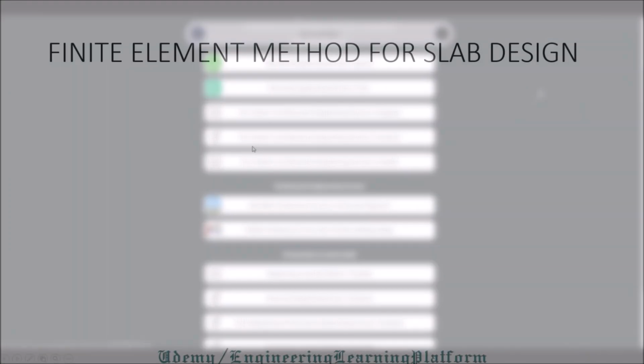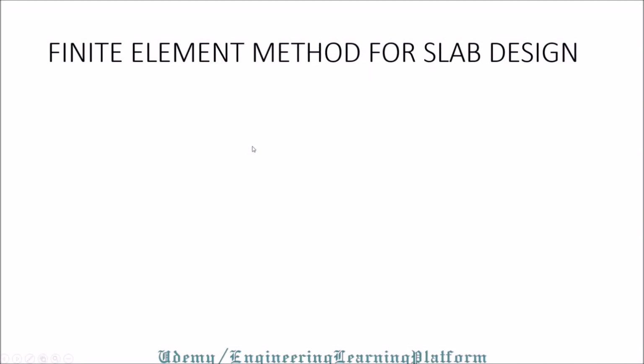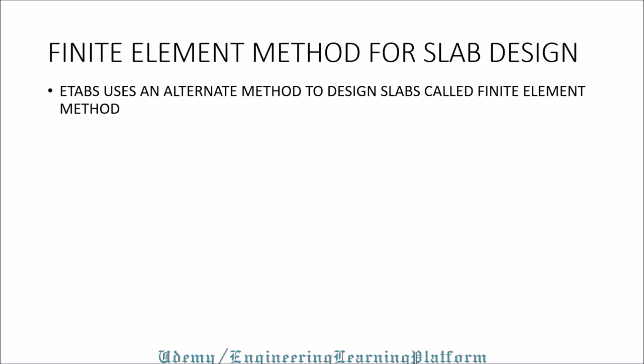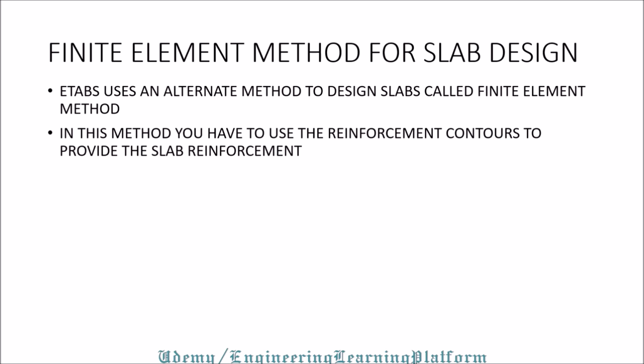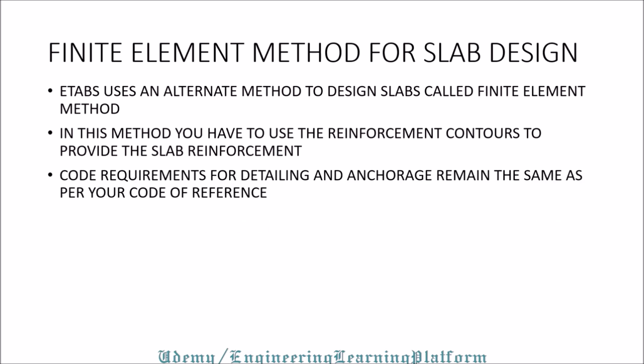In this lecture, we will learn about the finite element method for slab design. The finite element method is utilized by Etabs as an alternative method to design slabs. In this method, you will have to use the reinforcement contours provided by the Etabs output to add the slab reinforcement.